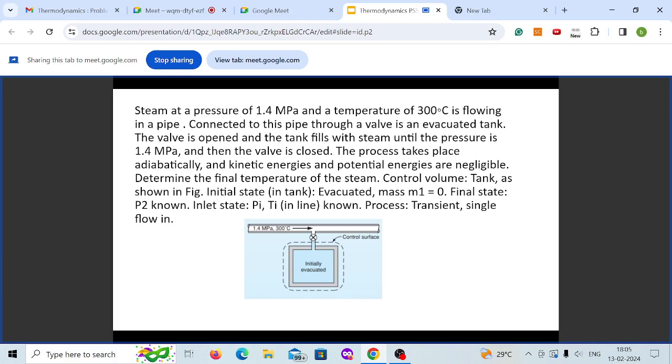Also there can be change with respect to time. In that, you account for how much the internal energy, or energy, of the system has changed with respect to time. So you write a dE by dt term to account for a change in system energy with respect to time in an unsteady case.